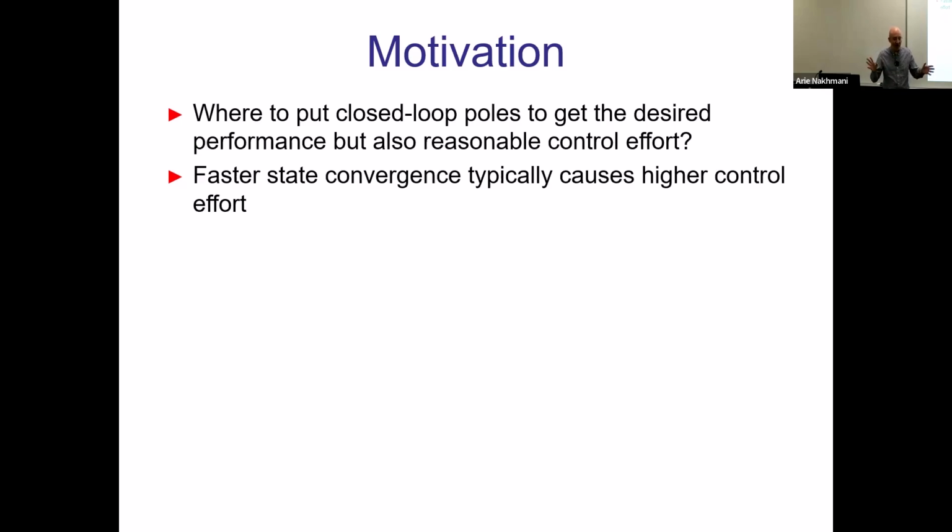So mathematically, it would be great. I mean, you have input of 1 million volts, fine, sure. It will converge in 1 millisecond. Like you have robotic arm, which is moving from that place to that place in 1 millisecond. Sure, mathematically. But physically, it's impossible, right? Because it actually needs time to move. So you cannot make it move without giving it strong power, strong force. But giving it that strong force, you can break it. So you will get to an area where actually your computed inputs for your designed controller are not physically possible or not good enough, right? So here comes a question like how we balance the both.